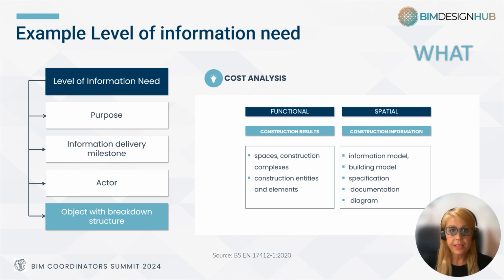Next, the objects with breakdown structure should be defined. The breakdown may include the federation strategy, systems engineering principles, and a classification system. The breakdown structure should also determine the project's functional or spatial decomposition into objects, for example, construction elements and spaces. Based on the purpose, the level of information need can be related to construction results and construction information.